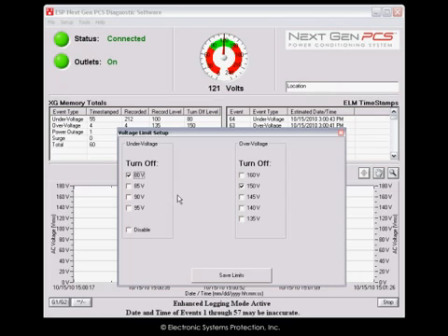For example, if he determines that he may have some equipment that is extremely sensitive to some type of over or under voltage event, he has the option here to set the over voltage cutoff limit, for example, at a top stop of 135 volts. And consequently on the under voltage side, he could set it as high as 95 volts.